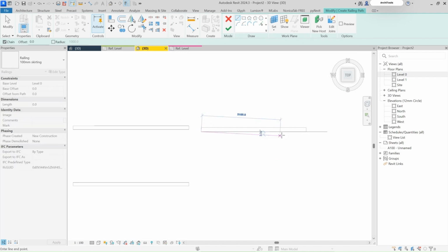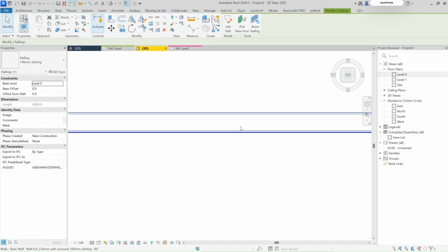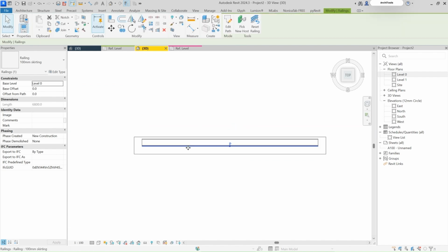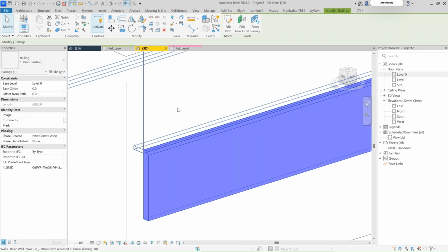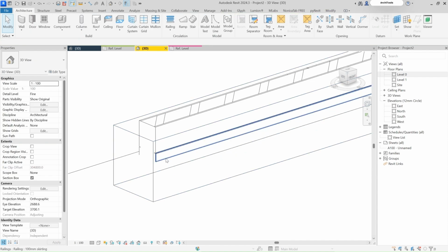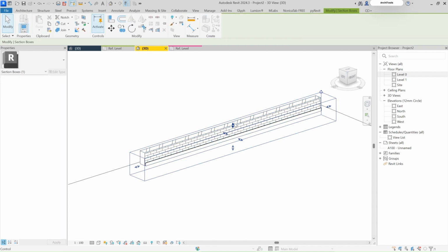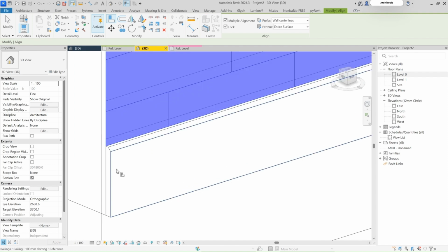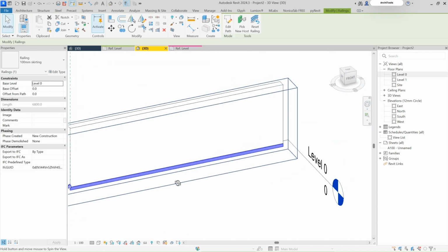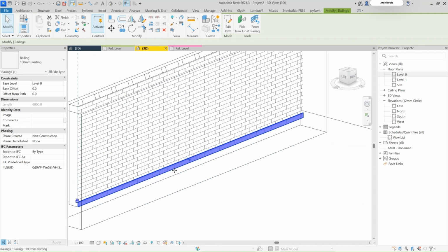Now, if you provide your railing as a sketch and just hit the OK key, I'll just go to the 3D and show it to you. This is the skirting that is provided over here. Let's just change the wall for your simplicity. Got it? So this is my skirting which I have provided using the railing method.